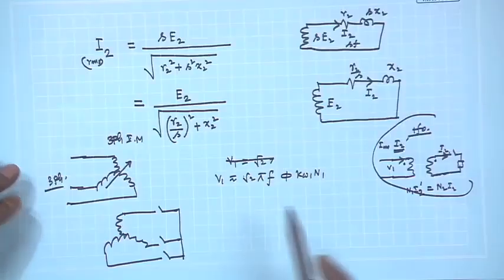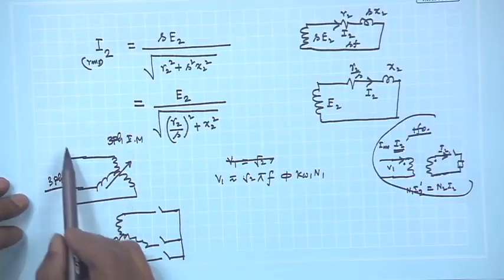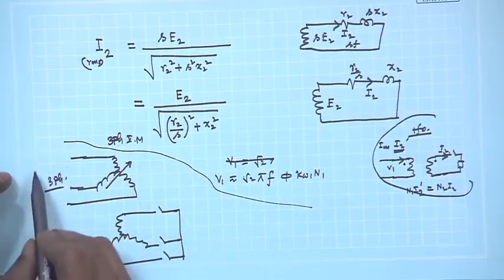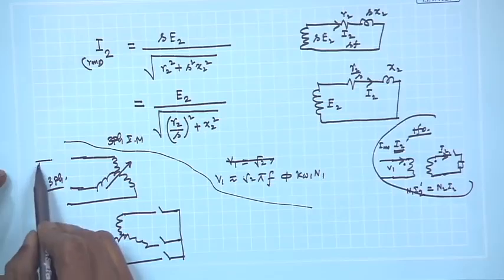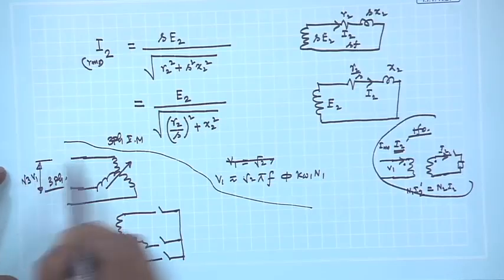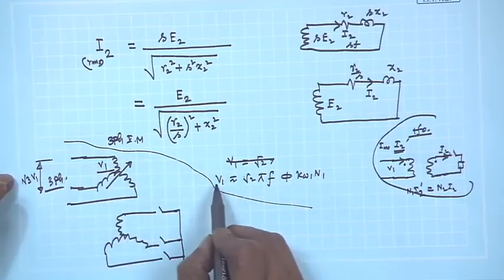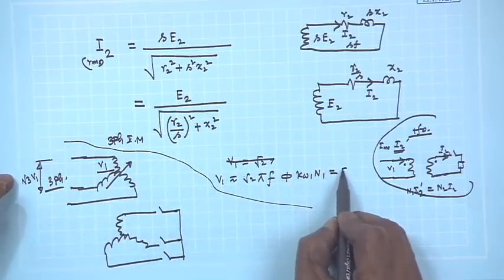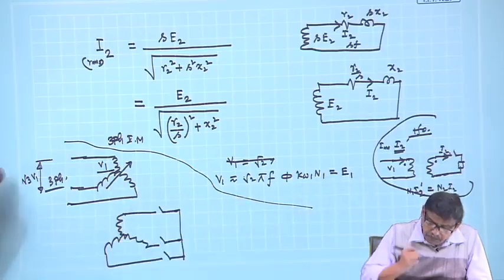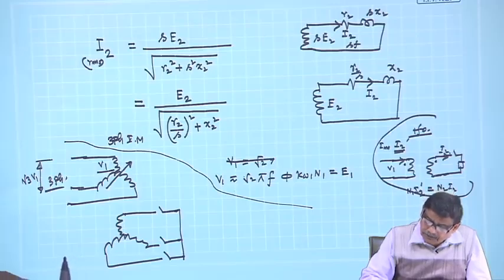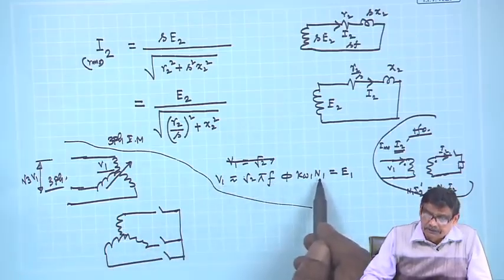Welcome. Let us continue from my earlier lecture straight away. I was talking about the 3-phase induction motor. Suppose you have applied line to line voltage √3 V1 to a star connected machine. So, per phase voltage is V1, and this V1 will be approximately equal to the induced voltage, because stator leakage impedance is small, as I told you. So, it will be closely equal to this.